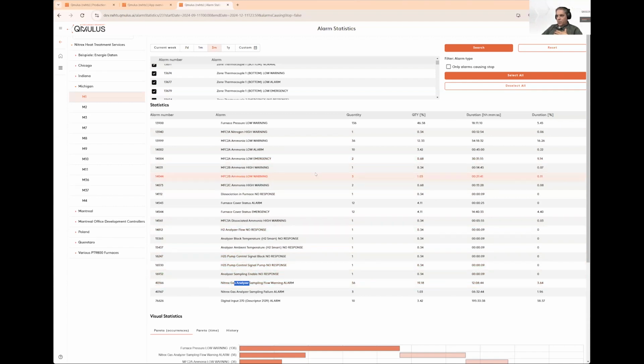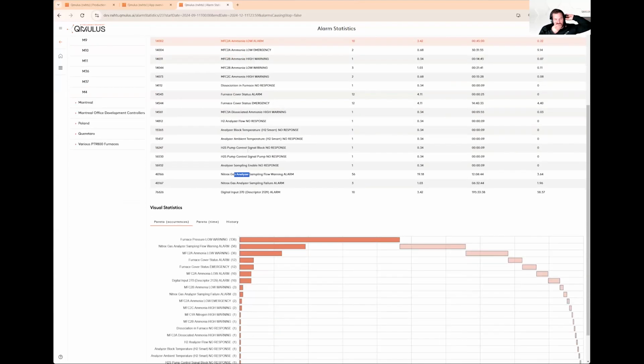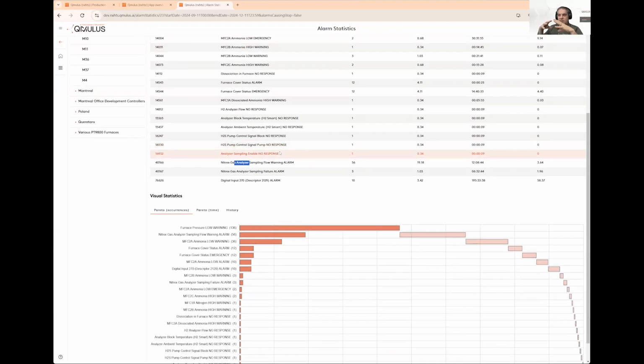So if I look at all this, what I see is in the last 3 months, I should be looking at this equipment and realizing, hey, maybe I should spend some time to take a look at ammonia mass flow controllers, ammonia filters. Well, I would check all the gas filters, all the solenoid valves, all the mass flow controllers, make sure all the lines are clean, make sure my gas pressures are okay, make sure my gas regulator on ammonia, let's say, could be starting to get damaged or dirty or something. Analyzer, I seem to have an issue here, so I need to take a look at that. Check my piping, check my cleanliness.